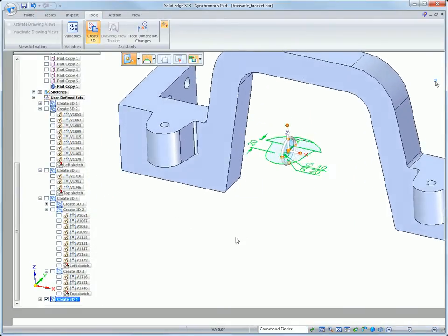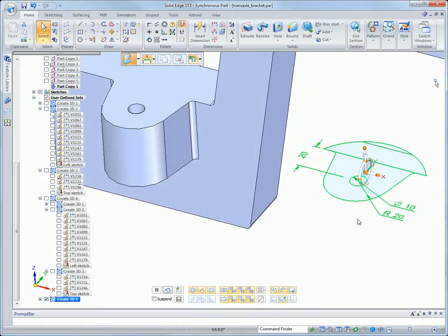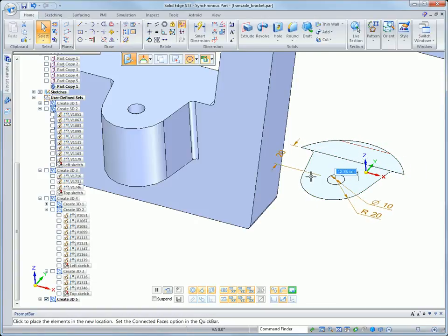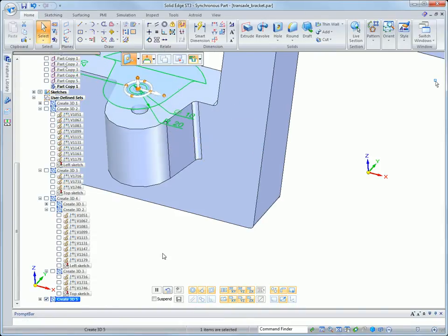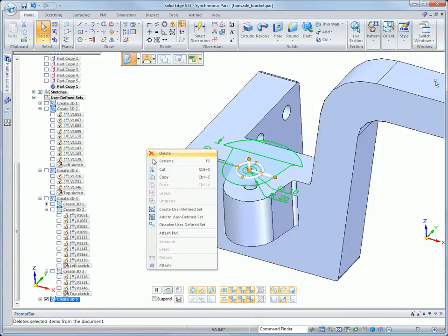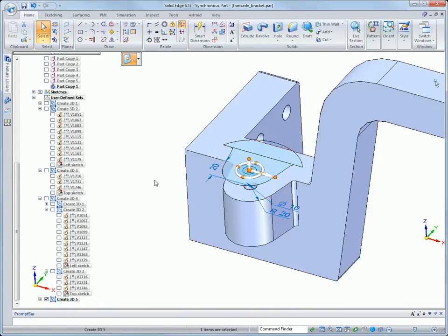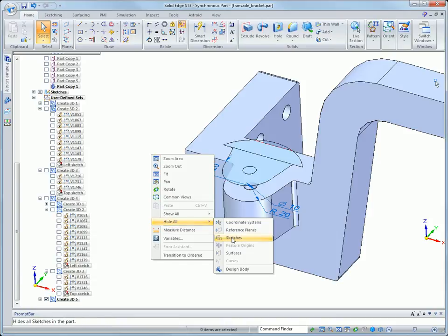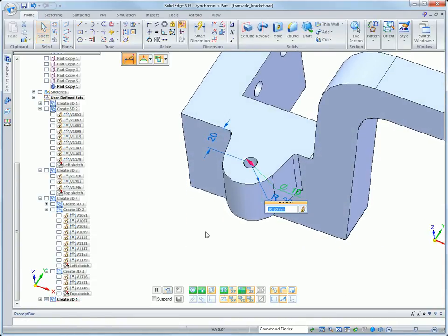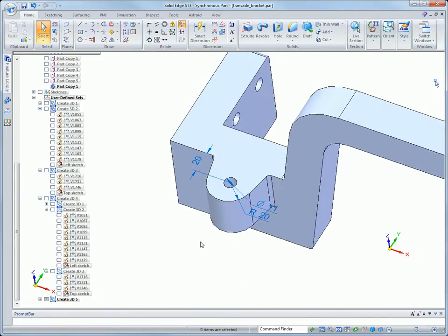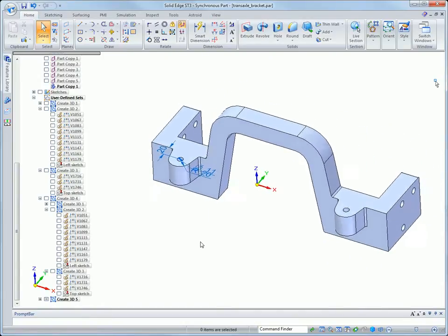See, it adds it to the 3D model, and we can move our steering wheel. We can reposition our steering wheel and take advantage of the synchronous technology to move this sketch within the plane and line up with a key point. This is true top-down type design. We want to attach those dimensions also to the 3D model and then make some changes. We want to change the hole size from 10 millimeters to let's say 11 millimeters. You see how it drives that 3D geometry from that manufacturing dimension.